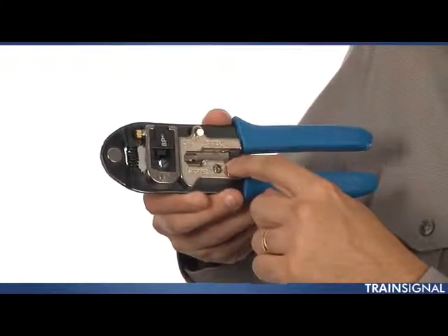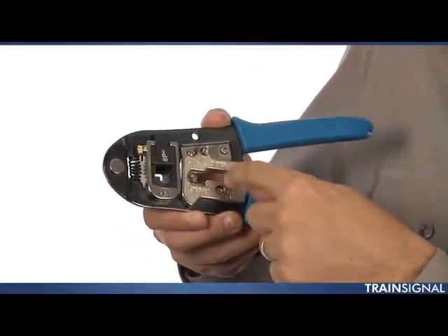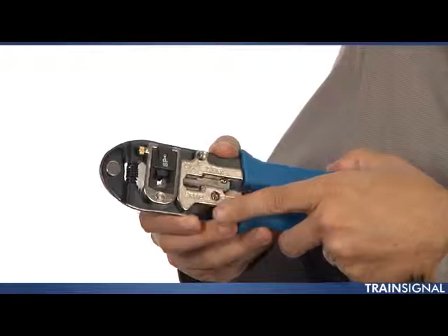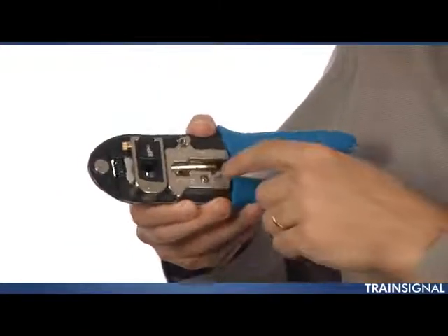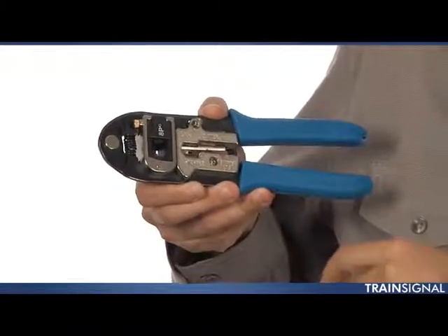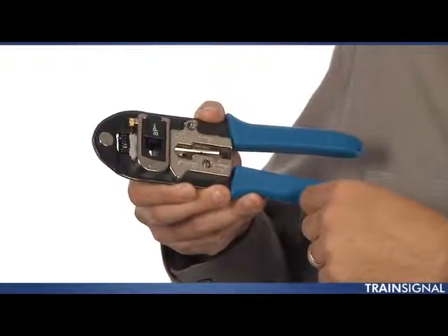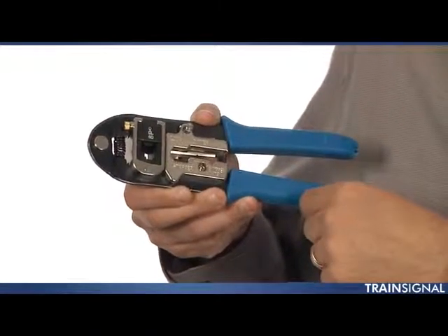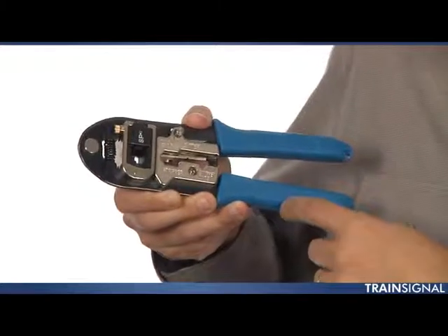The idea behind it, if we were to open this up, is if you put the Cat5 cable in there, and then you squeeze this down, and you just basically spin this or rock it back and forth, there's a blade in there, and it's just enough to strip away the outer coating of that wire. But the rest of the wire would be left in place, as far as the actual copper wires, the twisted wires inside.